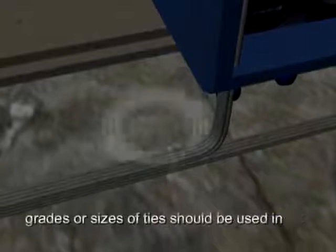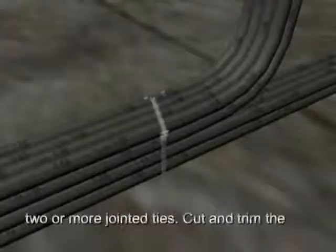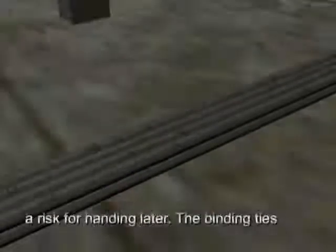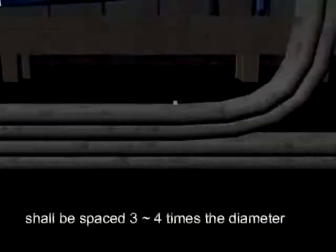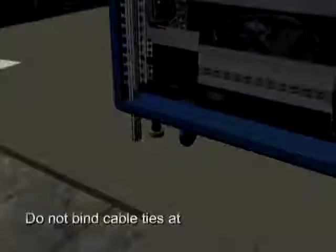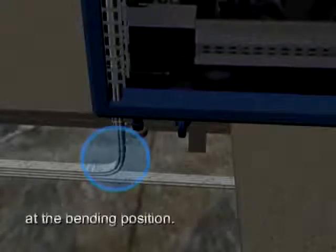Different grades or sizes of ties should be used in different cases. Do not bind cables with 2 or more jointed ties. Cut and trim the surplus part of the cable tie after binding to the root, avoiding sharp ends that may pose a risk for handling later. The binding ties shall be spaced 3 to 4 times the diameter of the cable bundle. See the installation guide for details. Do not bind cable ties at the turning of the cable bundle, to avoid that the inner core may be broken due to excessive stress at the bending position.